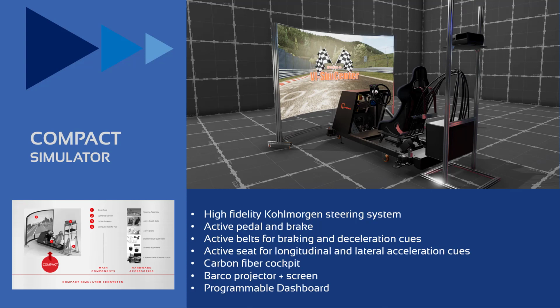The VI-Grade Compact Simulator is an entry platform focused on subjective response for vehicle dynamics. It comes with a high-fidelity Cole-Morgan steering system that is capable of accurate steering torque and feel response, so you feel the design intent of the model you're driving and not the simulator. This is done with an included calibration process that allows for canceling out all hardware-related torque effects to provide a more model-true steering response.